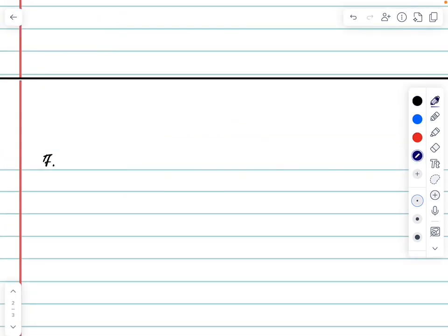And now we can find the current after 5 seconds. So the current also decays exponentially with the same time constant. So I'm using this formula, I initial e to the power of minus t over tau, and substituting the values we already have, this one.